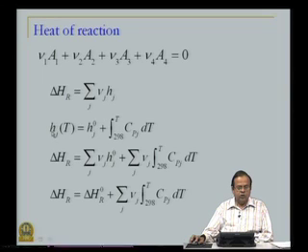So, partial molar enthalpy is a function of temperature, which we can relate to reference condition Hj0 plus integral from reference conditions, typically 298, to any temperature, Cpj dT. Cpj is the specific heat, which again is a function of temperature.